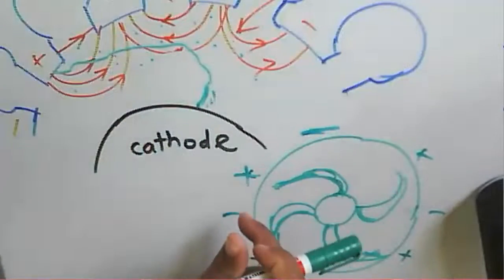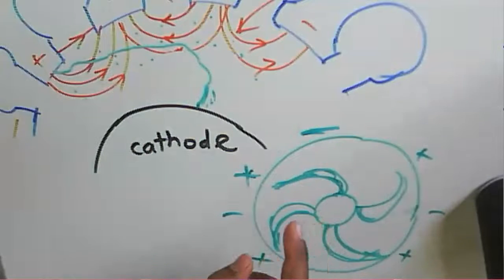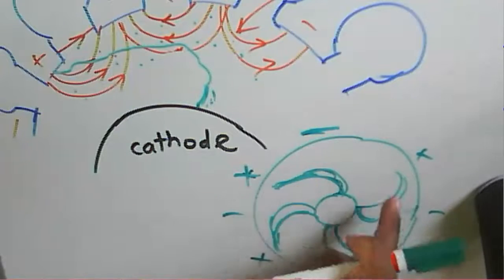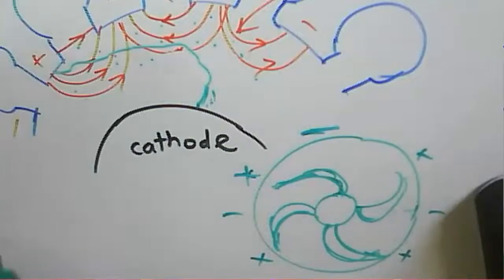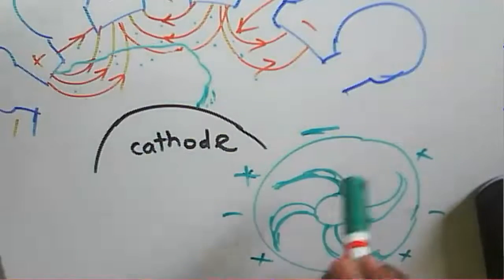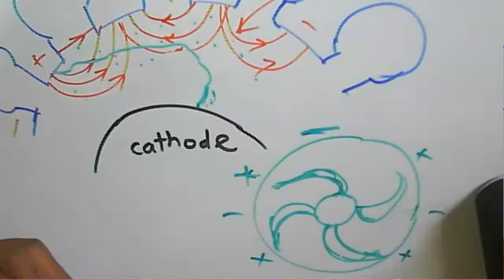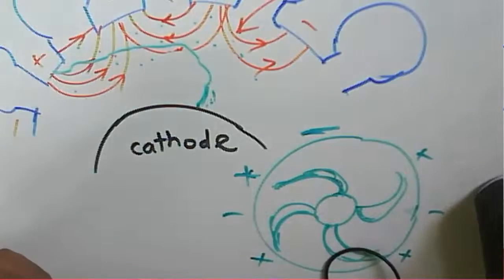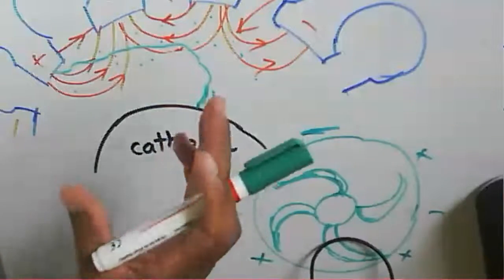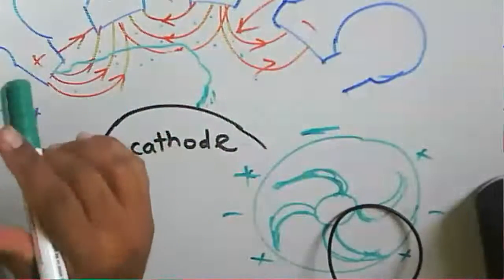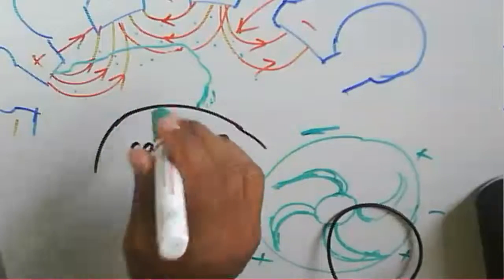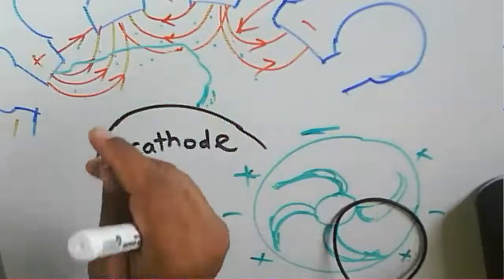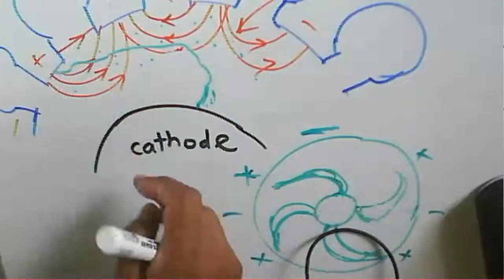Generally we consider the direction to be clockwise. So likewise we consider it, but this one is about spokes like that. This is what we can say is an electron orbit now. So that's all about the magnetron here. In a magnetron, we consider an RF field, that is an electric field, as well as a magnetic field, in which magnetic flux lines are passing through the cavities and are parallel to the cathode axis. Now this is the cathode axis.